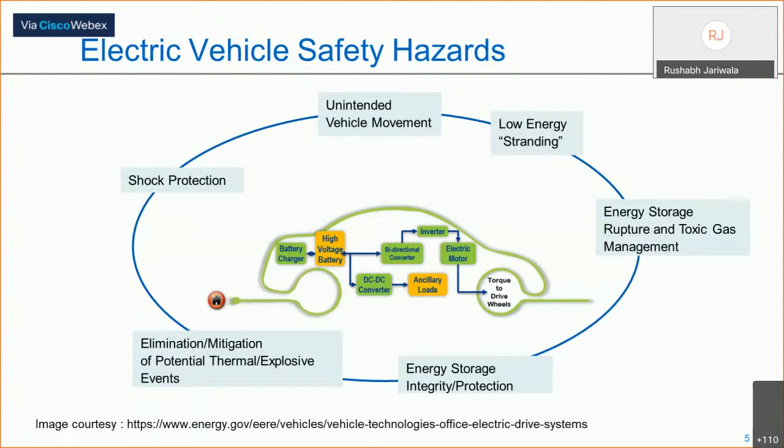It's not that simple, because any false start can also lead to unintended vehicle movement. Then another thing is a new kind of hazard, what I would call low energy stranding. In the electric vehicle, the OEMs and whoever is responsible have to be very careful to show the state of charge remaining in the battery while the driver is on the road, because